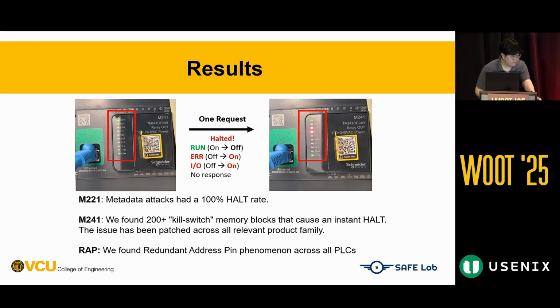Now, a fair question might be raised. Were we just randomly poking the memory until something broke? The answer is that the critical data region that we classified is less than 1% of the whole memory space. And when we attack it, we didn't modify the whole data chunk.